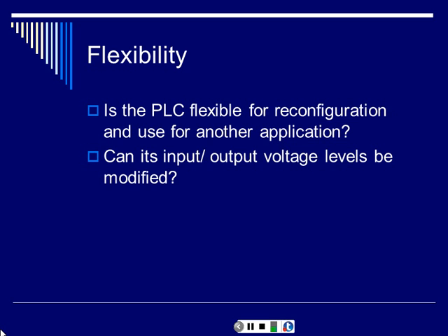If I'm going to purchase a PLC, I think there are 8 outputs on this guy, I'm guessing. But let's say there are 8 outputs on this thing, and I know already that I'm going to have 9 things that I need to run.